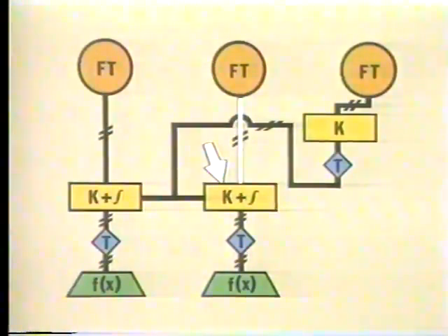This controller is a PI controller. It's essential to have the right amount of air in the furnace to ensure complete combustion. And a PI controller ensures that airflow is maintained at set point. The output from the airflow controller goes through this hand auto station and on to the final control element.